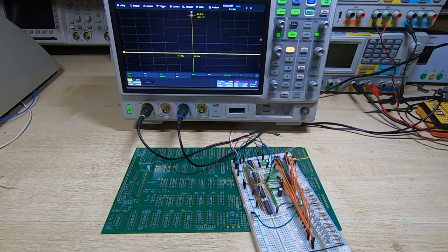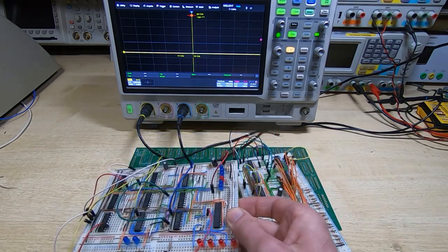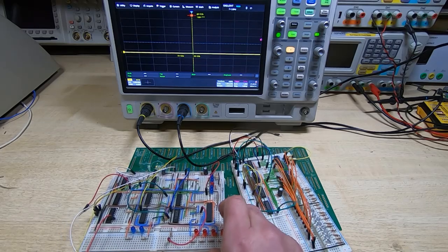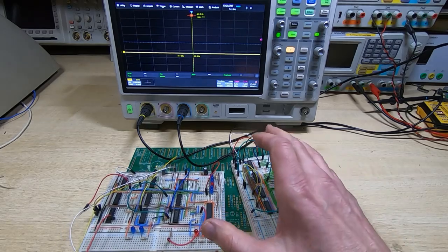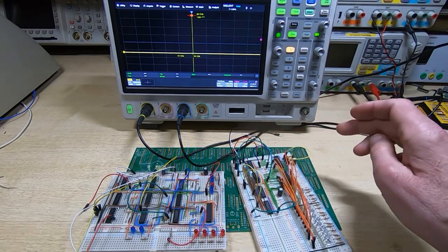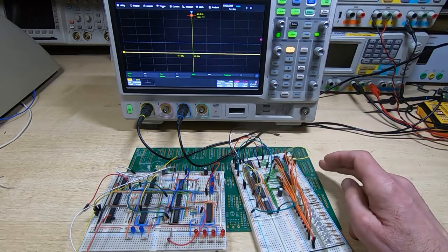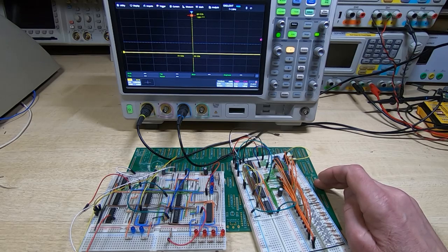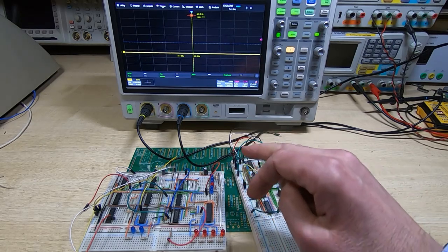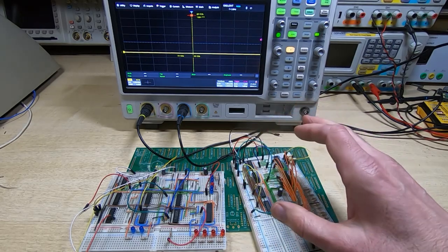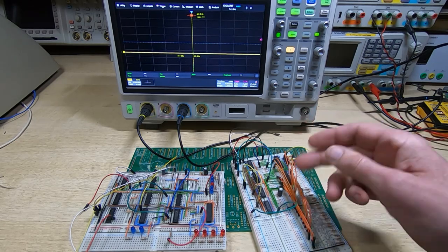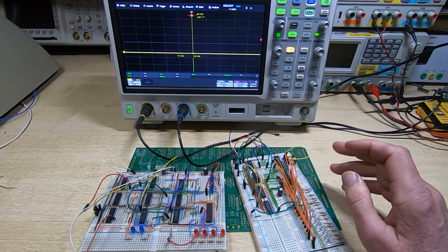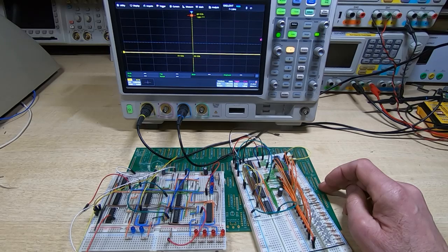We also need to add some relatively complex control for that DMA system, and also I want to make the new board compatible with the version 4 board, in as much as I want to be able to enable or disable the DMA system so that the floppy drive interface can be used using programmed in-out.